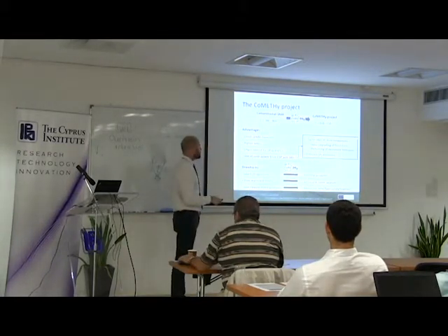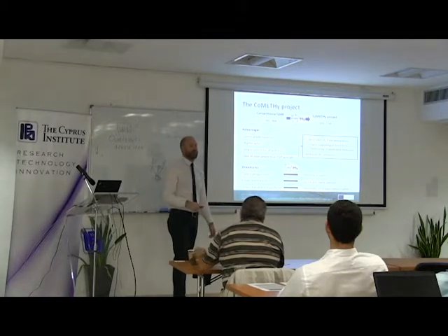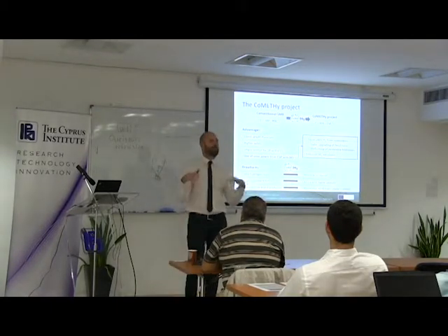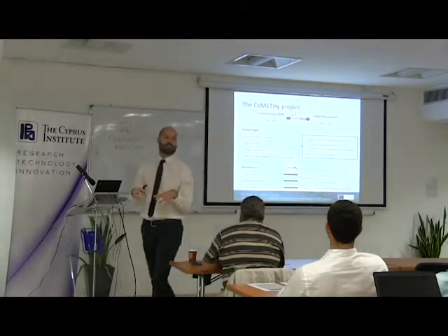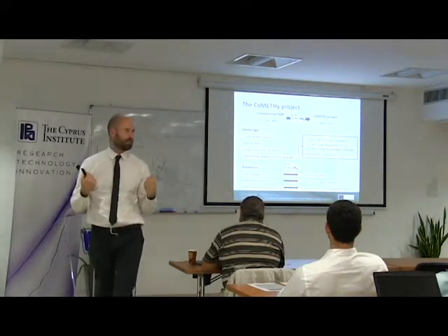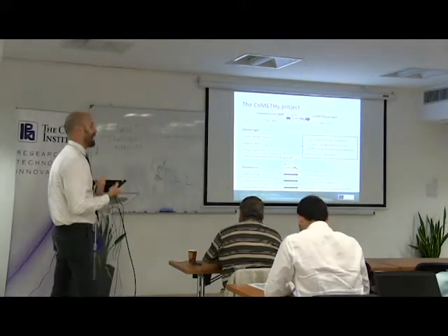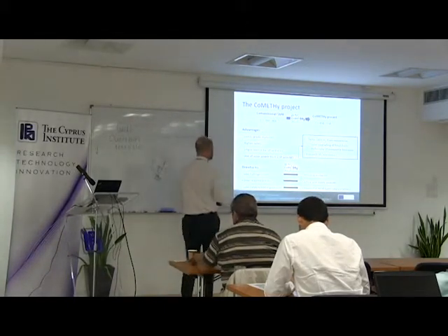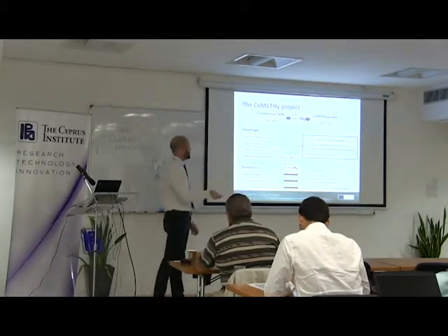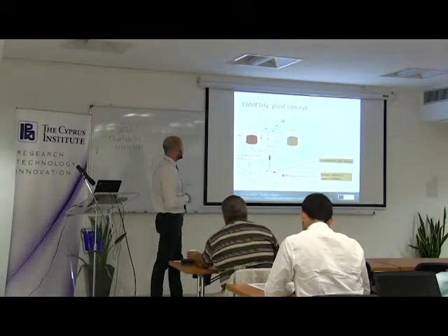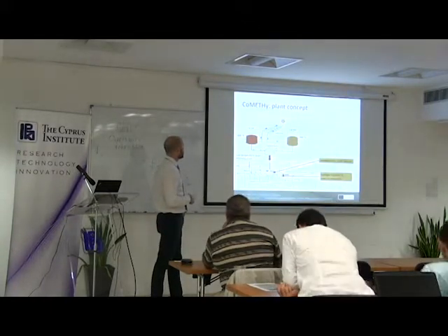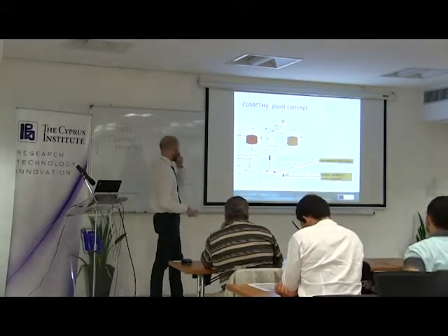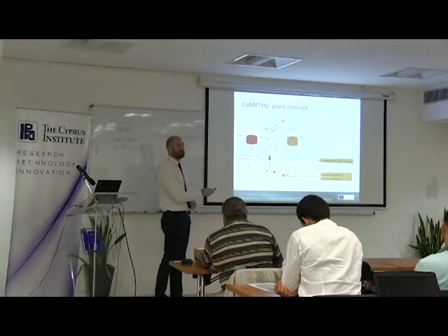So what has been used in this process is a membrane reactor. There is a membrane embedded in the reactor, in the reaction space, which extracts hydrogen from the reaction space. And this allows us to push the conversion. Then also active catalysts were developed and also the catalyst carriers.